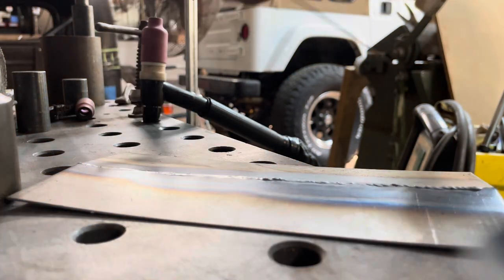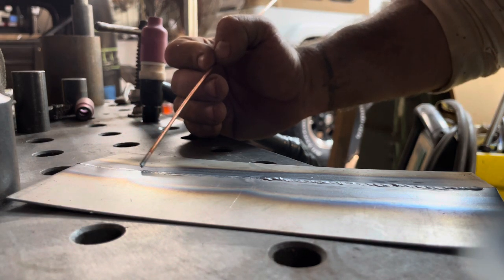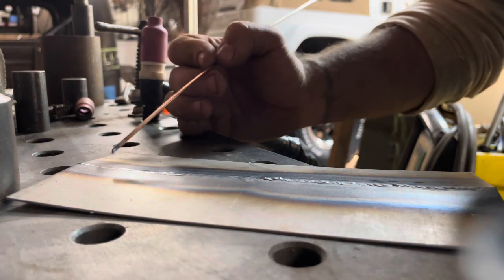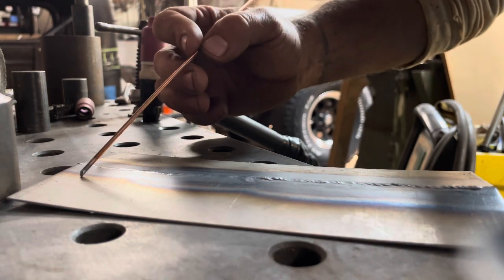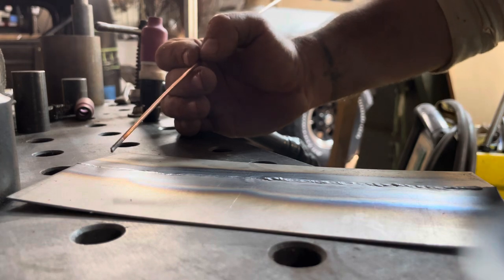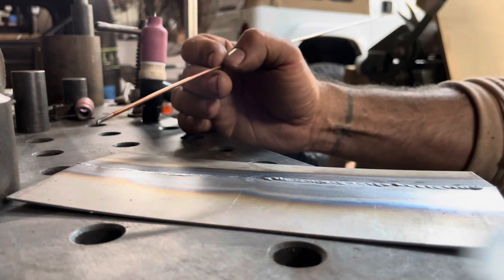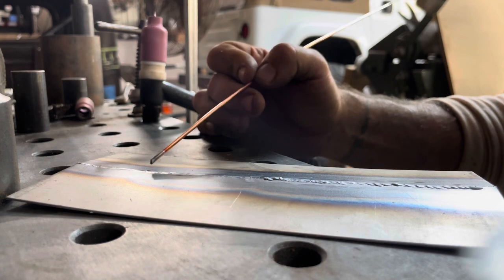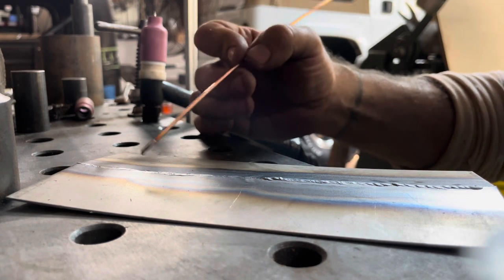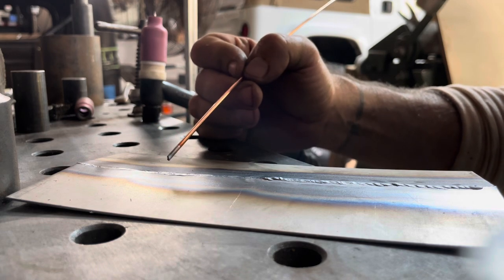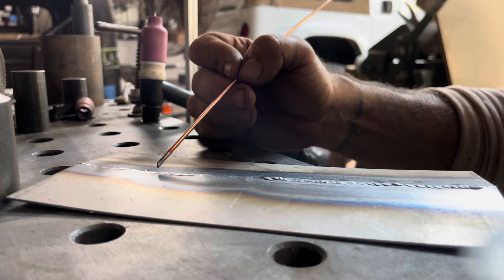So this very beginning part, I only did a fusion. And you can see I had to put less heat input into it because the filler was not cooling the puddle. The next section from here to here, I have a much larger heat affected zone. I had to use more time in order to allow the puddle to get hotter in order to get good fusion.